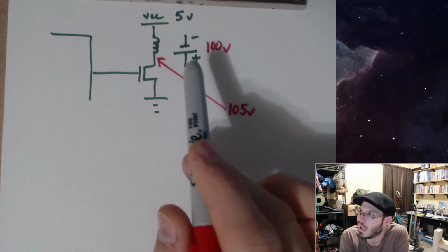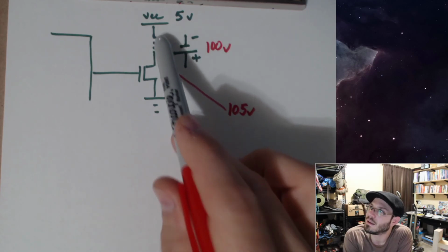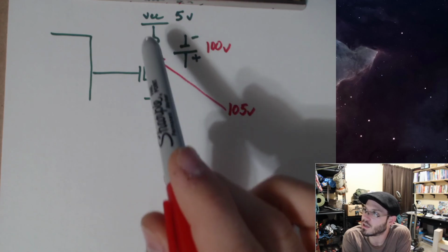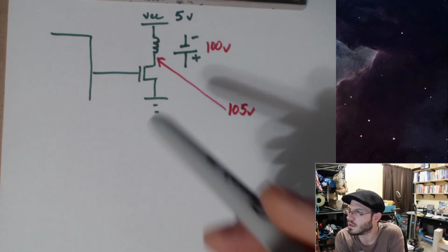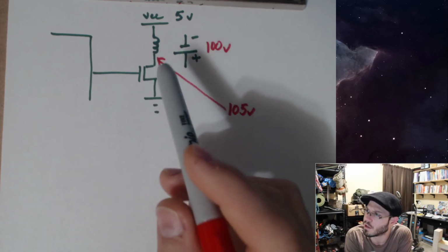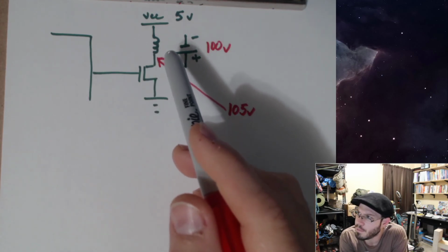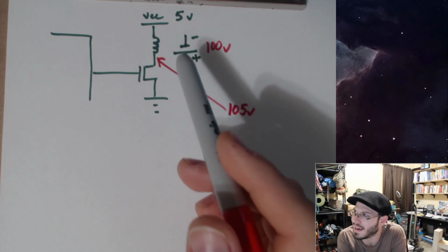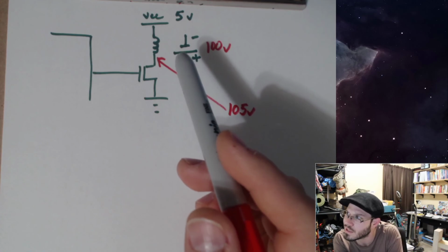What limits it is the resistance of this inductor, the practical considerations, what we generally regard as the parasitic properties of a component. If I had a pure inductor, it would have 0 resistance, but I can't have a coil of wire that has 0 resistance, so it has some resistance.